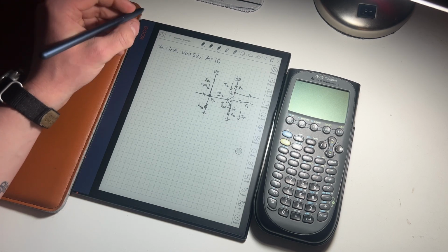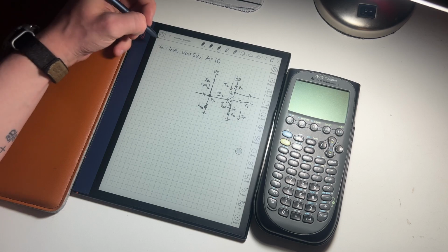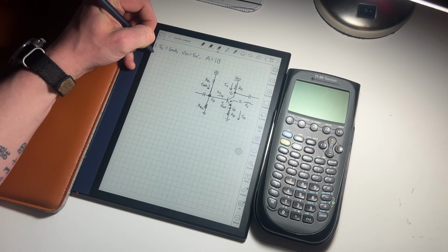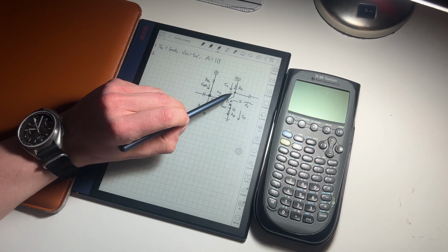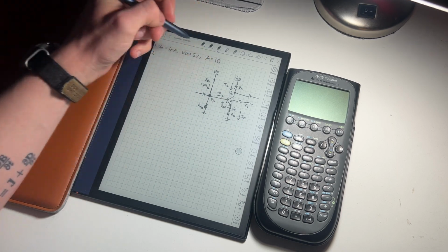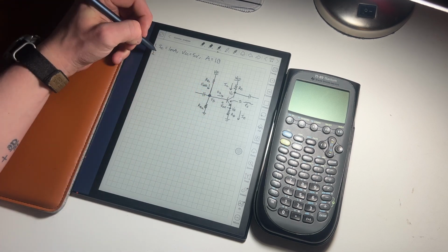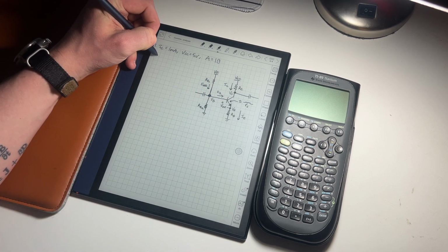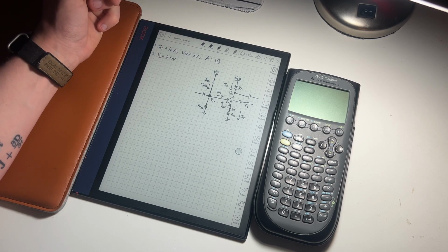So we've already completed step 1, which is set IC. Step 2 is to set RC such that VC is roughly your supply voltage over 2. So I want VC equal to 2.5 volts.